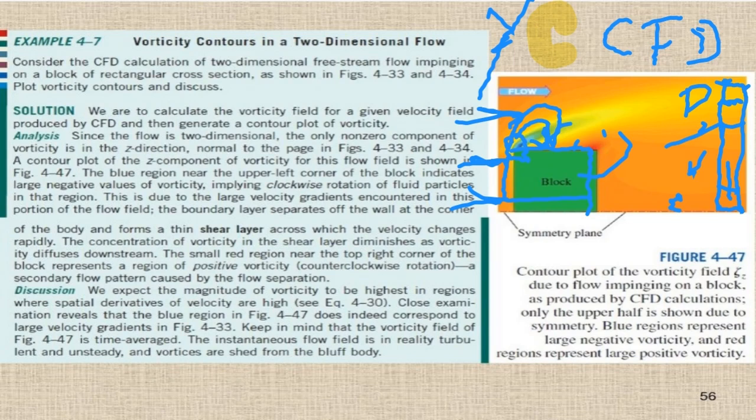Because it has a flat back like this, and because of this flat back, there is a vortex or vorticity at the back of the car, which will create a vacuum, and this vacuum will suck the dust and will make this window or glass dirty. That's why you need a cleaner there, and you don't need that in a sedan car. So in the front, you have a clockwise vortex, which means it's negative. It's like this, clockwise. On the other hand, at the back, you have a counterclockwise vortex, which means it's positive.